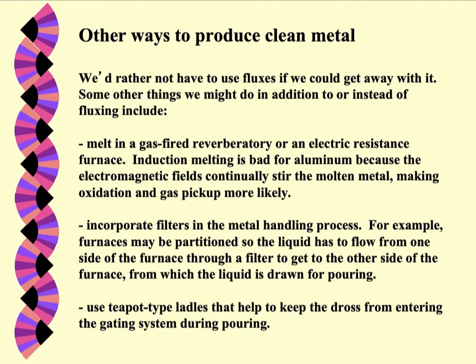How else can we clean the metal up? If we melt in an induction furnace, the induction furnace we have, and I may have mentioned this, it magnetically stirs the metal. I think I had you look over the molten metal the other night, and you saw it made a big bubble on the surface, and the metal is stirring around very quickly. What happens is you form oxides at the surface, and they get drawn down inside the metal. So it's not a good process for melting aluminum.